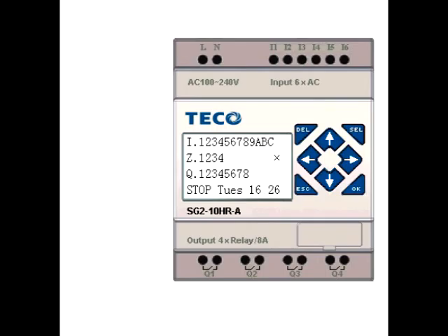One of the other important features you can see here in the lower left corner, it says stop. That means that this control is in the stop mode, and you can change all the variables in the software, but it's not actually running, and it won't run the machine. It needs to be in the run mode. After we go through the different setups here, we're going to come back to that and put it in the run mode, because I have something interesting to show you about that.